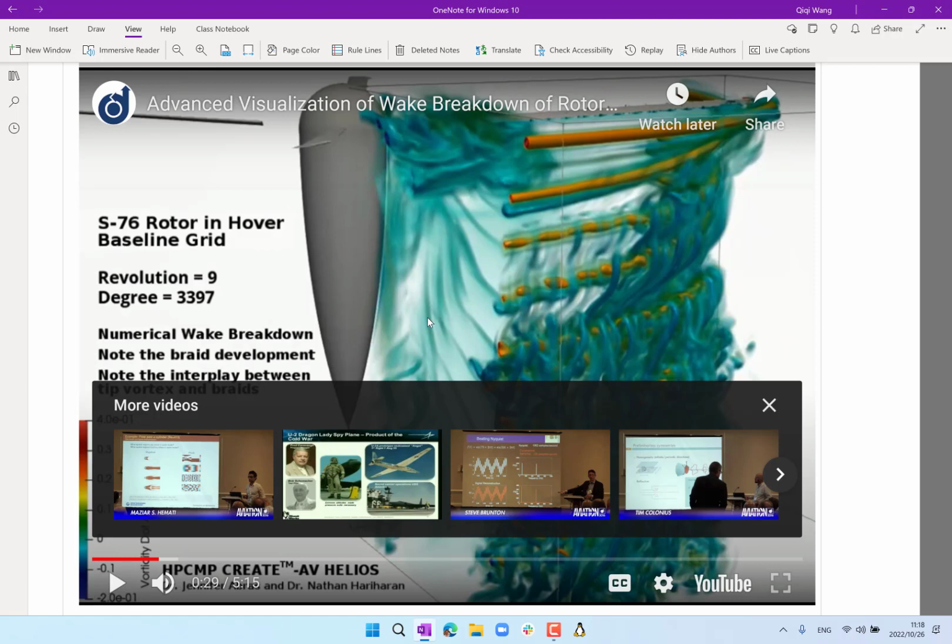And then, as we have studied, the kinematics of vorticity does not allow any circulation, any vortex, which in this case lies within this blade, to end at any point. So the same amount of circulation has to come out as a vortex. So that's the tip vortex. That's clearly visualized over here. All right.